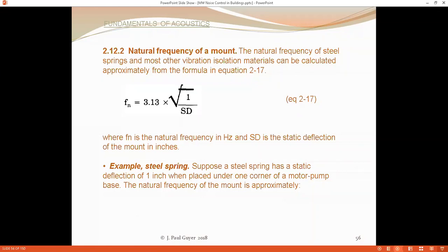Now, these vibration isolators can be just like a rubberized type of pad, or they might be these spring type vibration isolators, which are just a spring inside of a housing, and the frame for the fan is set on 4 of these vibration isolators, and that isolates the oscillating fan from the structural elements of the buildings, the deck, the beams, the columns, this sort of thing.